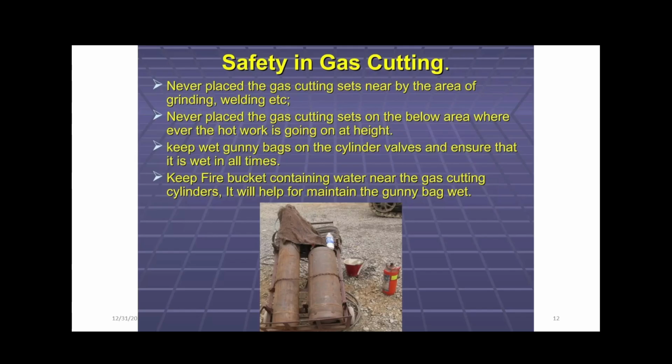Ensure you keep wet gunny bags on the cylinder valves and ensure that they are wet at all times. You also need to keep fire buckets containing water near the gas cutting cylinders. This will help in keeping the gunny bags wet.